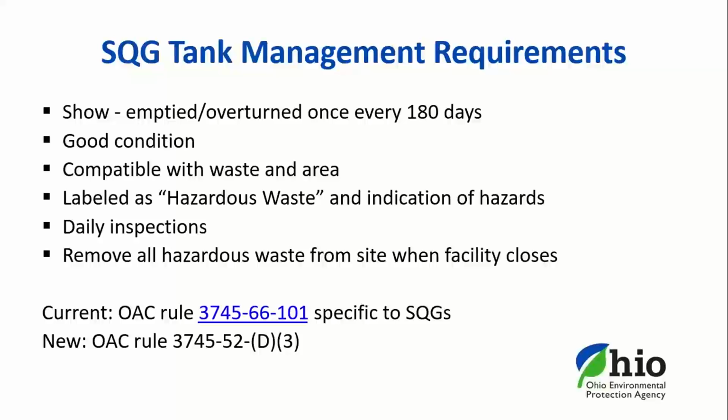Hazardous waste or treatment reagents shouldn't be placed in the tank if they could cause the tank or its inner liner to rupture, leak, corrode, or fail before the end of its intended life. And upon closure of the facility, the hazardous waste needs to be removed from the tank, as well as from the discharge control equipment and from discharge confinement structures.